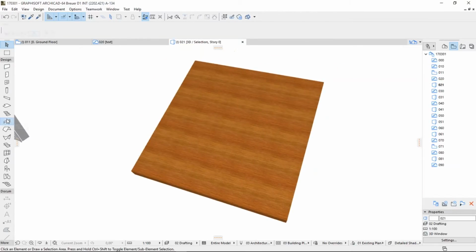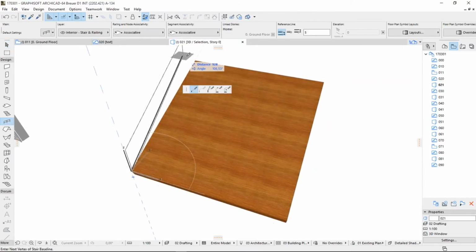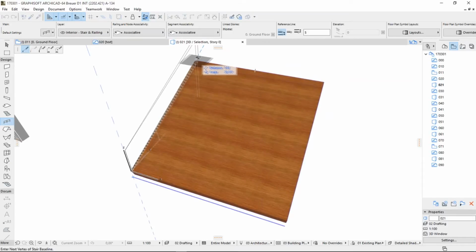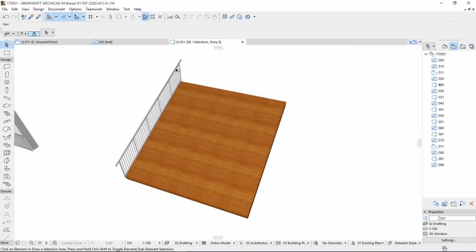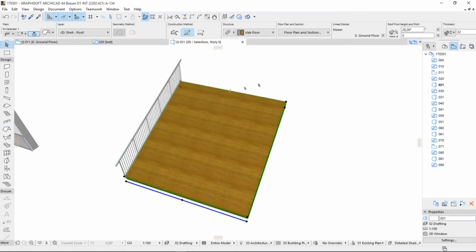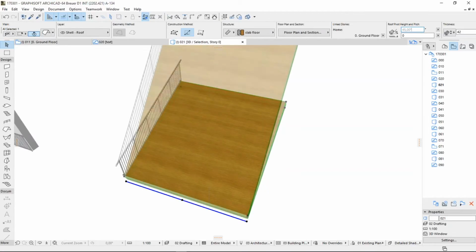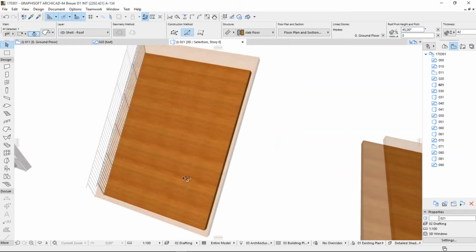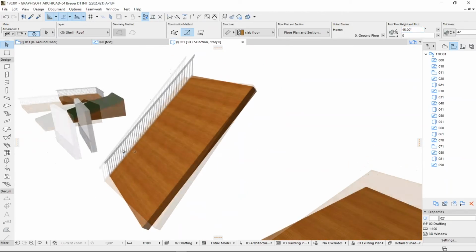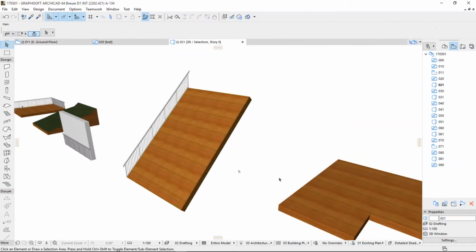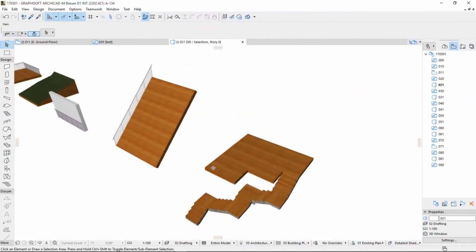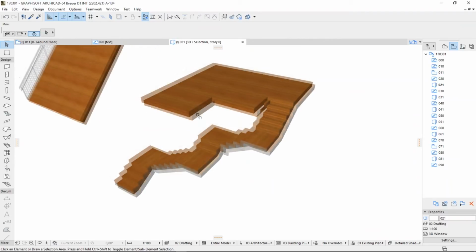Of course, I have to have a railing that is only one top rail, for example. I can attach a railing to the slab. And of course, you see that it's always highlighted, so whenever I attach a railing to a host element, it always gets highlighted, just like if you use the dimension, meaning that it's associative to it. Now, if I change the steepness of this roof, you can see that the railing follows that, and of course, it follows all sorts of curvature changes.